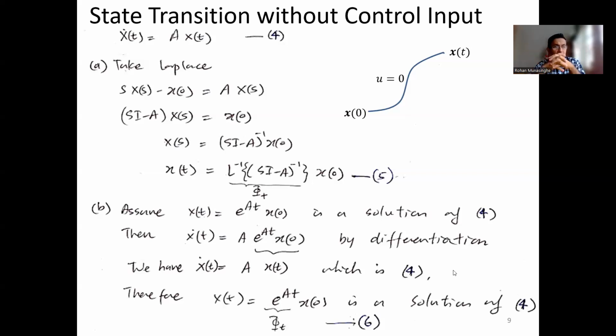Well, it depends. You can say, if I want to control acceleration up to that level, then that is also a monitored variable. But I'm referring to generic cases, where you have a differential equation of any order, and you assign state variables and write down the state equations. You build the state space model. In the mass spring damper system, the acceleration is directly connected with the external force. Whatever force you give to the system is going to change the acceleration first, and as a result velocity changes and then the position. Therefore, what we regard as state variables are position and velocity. The acceleration is not regarded as a state variable.